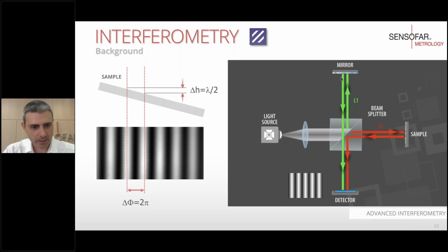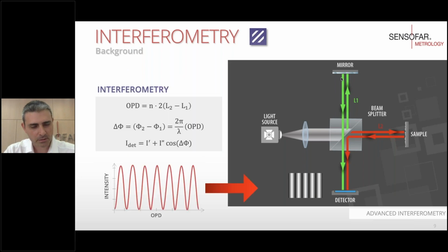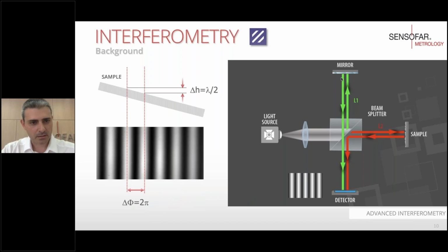So we have to go back to that equation, the middle one. The light travel from the beam splitter to the sample for the white part of the bars is exactly the same, multiplied by lambda over 2. And what happens in the middle? The dark bar between the white bars means that the height tilt, the travel between the reference mirror and the sample, equals lambda over 4.